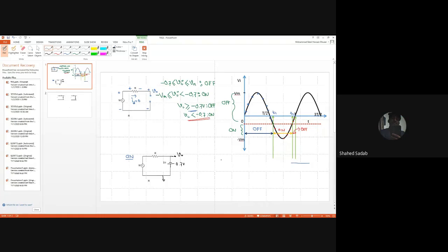This 0.7 volt is another terminal point, the minus point. So if I start my cable from here, starting from plus minus, then it goes minus 0.7. I assume plus minus V naught is equal to 0. So that gives us V naught is equal to minus 0.7. Which means I can straight away find out the input output relationship.